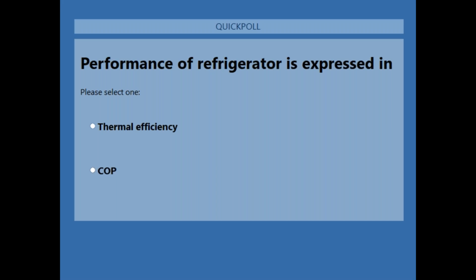One more concept at the end we had discussed is the coefficient of performance. Coefficient of performance is a way of capturing the performance of a refrigerating machine, and it is different from efficiency because we are not talking about a conversion efficiency. It is basically talking about how much cooling effect a refrigerator gives you, that is QL, upon the work input to that machine. So QL upon W is the coefficient of performance of a refrigerating machine.